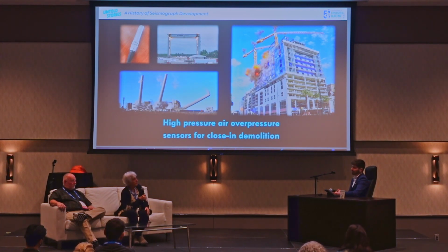So I think with that evolution of seismographs, faster timing rate, more memory, what else? More memory, faster, low-end resolution. Better at the low end for far away. That really helped. So now we have a wide spectrum of abilities to do both close-in and far field to improve on our performance of the explosives. So it's a feedback loop. Yeah, it works very, very well. We learn, the blasters learn. So I think the seismographs have been very helpful for our business, certainly, and I think for the blasting industry as a whole.